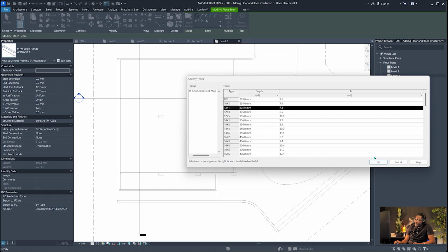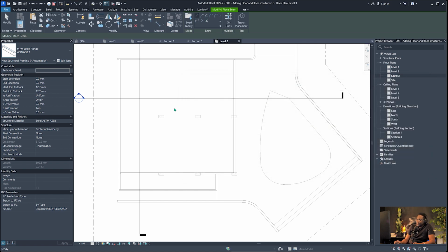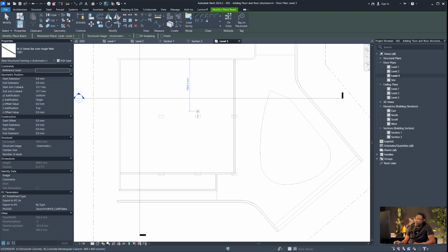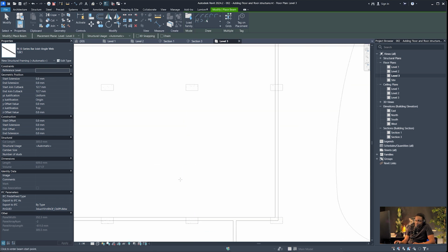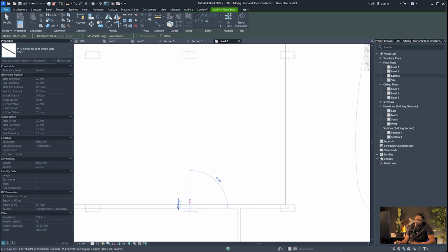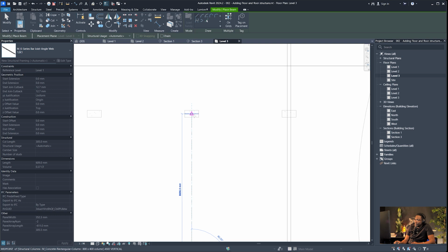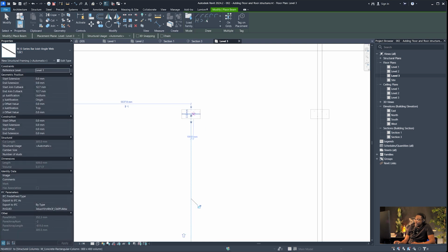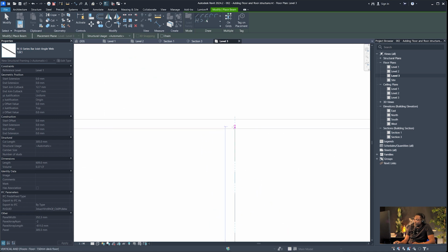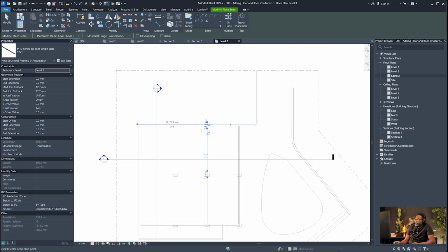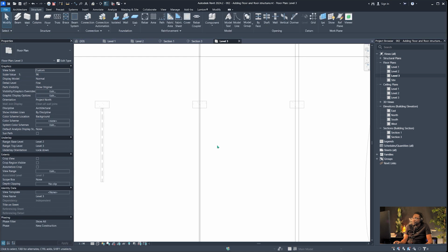12K1. Now, as I said, usually if we're doing this in architectural drawings, it's just to represent the beam. Remember how Revit is meant to work. It's really meant to work collaboratively, which means that your engineer is also using this very same drawing, and they would be the one to specify the beam. All right, so I'm going to put one that goes across like this. And I can put another one that goes across like this. I'm going to stop it in the center of the wall. All right, I'm going to make sure that this is set to fine detail, so I'm actually seeing the beam there. I'm going to press escape.